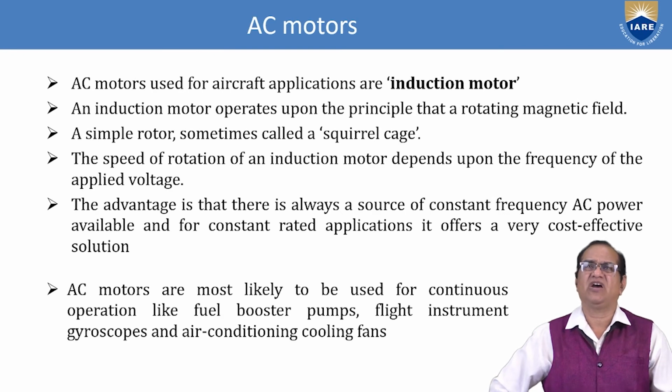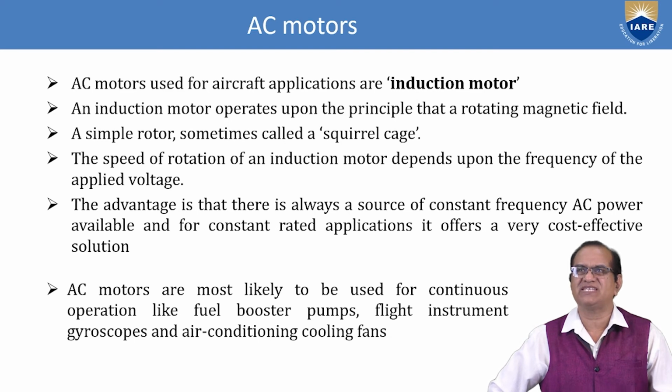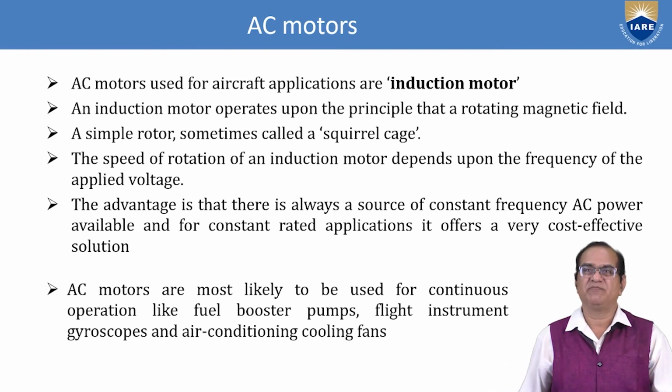AC motors, we have AC motors used for aircraft applications are induction motors. An induction motor operates upon the principle of a rotating magnetic field and a simple rotor, sometimes called a squirrel cage. The speed of rotation of the induction motor depends upon the frequency of the applied voltage. The advantage is that there is always a source of constant frequency AC power available, and for constant rate applications it offers a very cost effective solution.